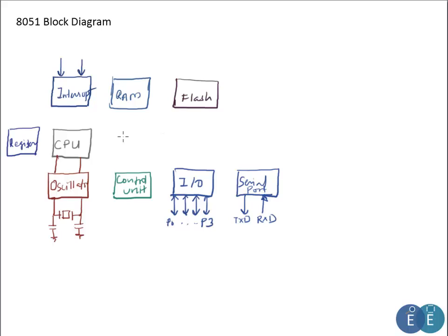And apart from all this, you have units which handle time, which are used to measure time internally, or even to count external events. These are called the counter or the timer unit. So in 8051 we have a timer and a counter inbuilt. If it is used as a counter, then the input would be from an external pin. We'll see this in detail in just a while.